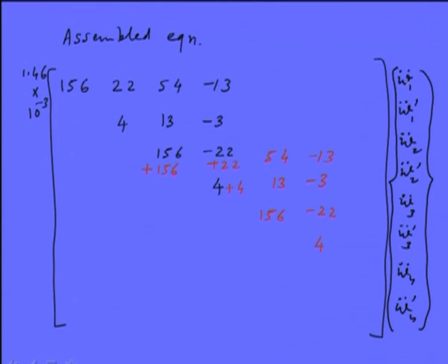You can see that the first 4 entries in this vector correspond to element 1, and element 2 contains node 2 also. So there will be overlapping when we assemble elements 1 and 2, especially at node 2, which is common to both element 1 and 2. These are the overlapping terms we can see.